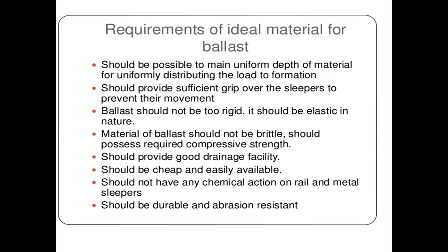What are the requirements of an ideal material for ballast? It should be possible to maintain a uniform depth of material for uniformly distributing the load to the formation. It should provide sufficient grip over the sleepers to prevent their movement. Ballast should not be too rigid. It should be